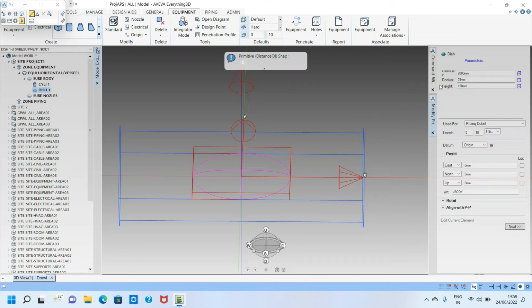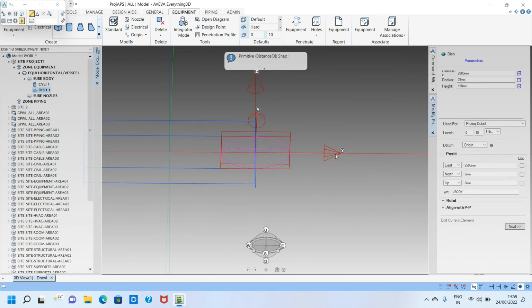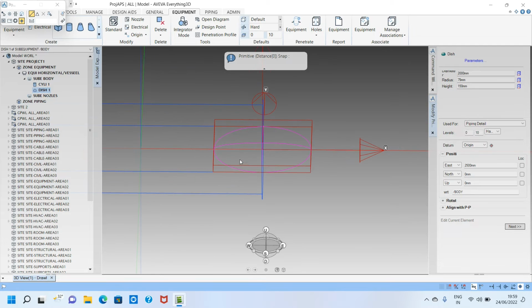by the command method. For example, the cylinder is 5000, right? Now it is in the center of the cylinder, which means it is at 2500. So I have to move east by 2500 here. I can put 2500 here. Enter. So it came here, right?